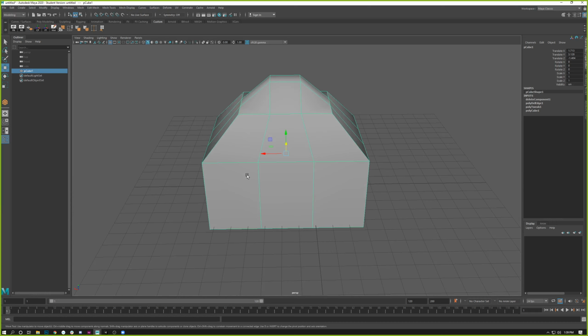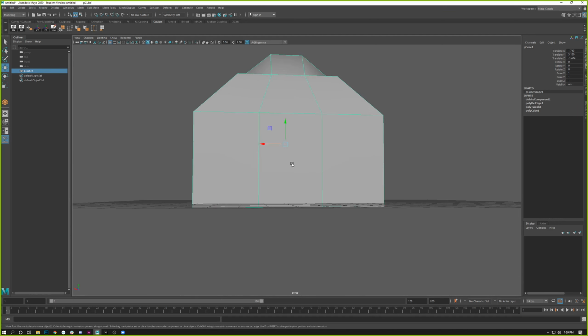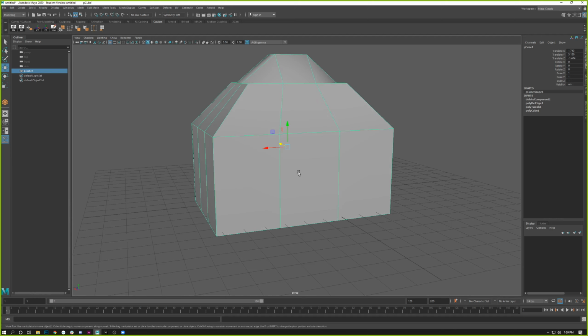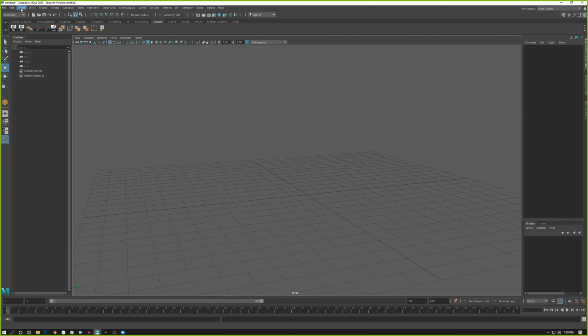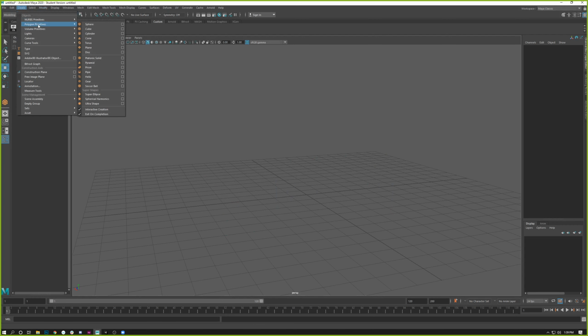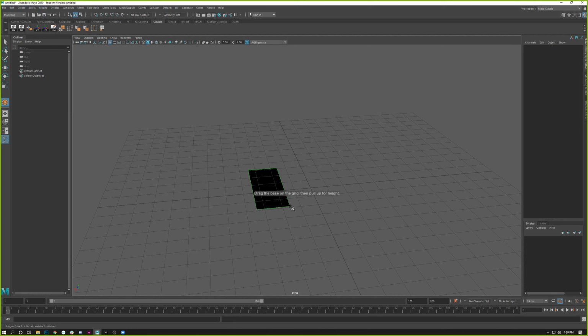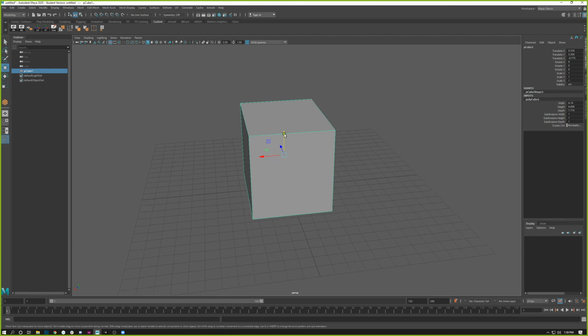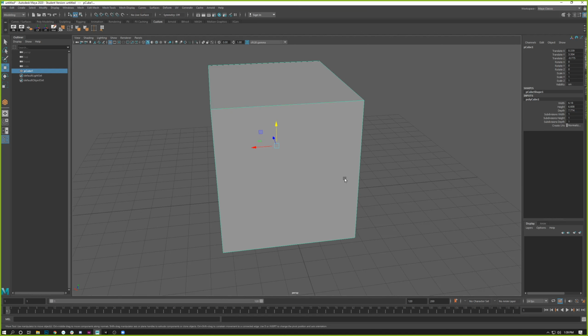What you do instead is you use tools. Maya is really good at this aspect of doing it. And they recently combined all the tools they had, for the most part, into one tool. I'm going to go ahead and make something simpler for this. We'll start with just a plain cube. So what they did is they combined them in one tool, and I believe the default quick key is Control-Shift-X, and you get this little X-Acto looking icon.